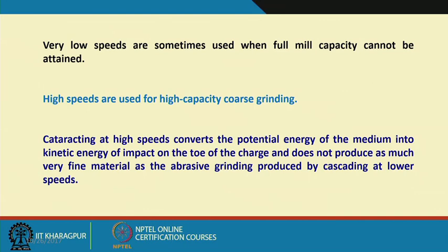In that case, maybe we can reduce the mill speed so that my capacity is matched, because your mill operates at the best condition when it has an optimum feed solid concentration inside the mill.